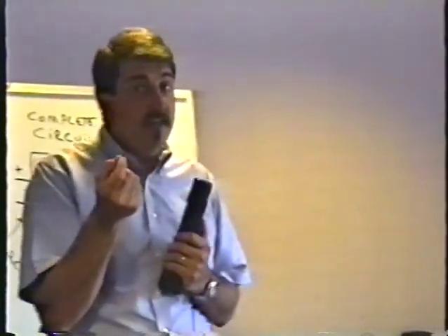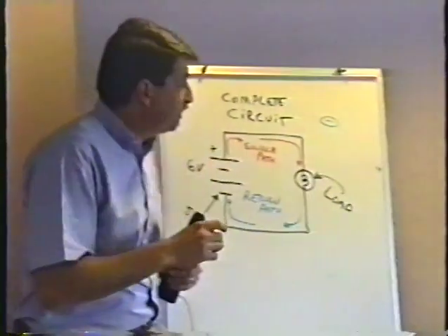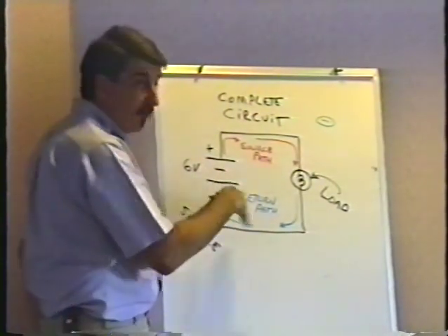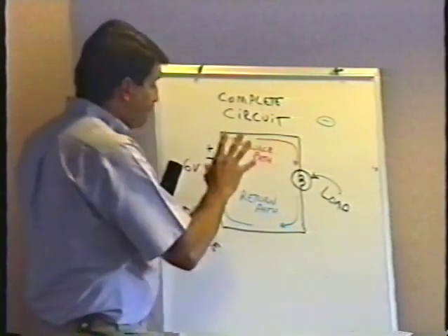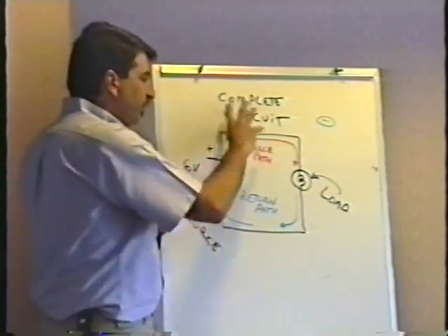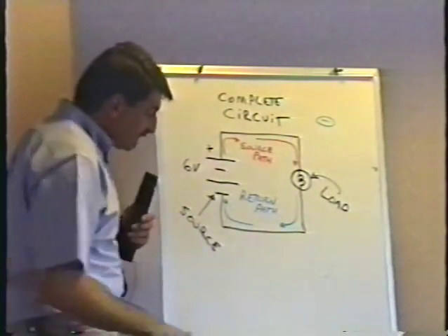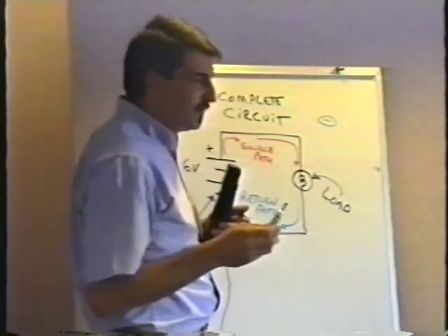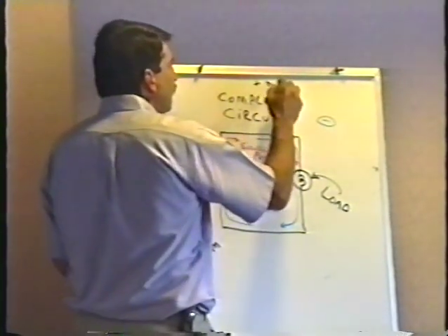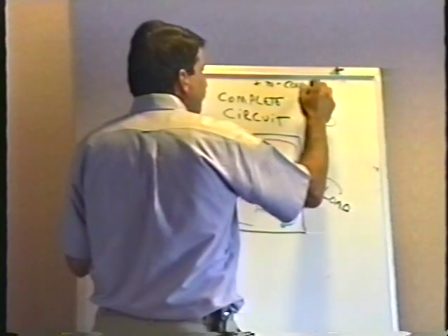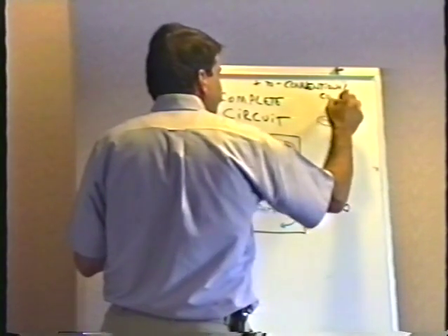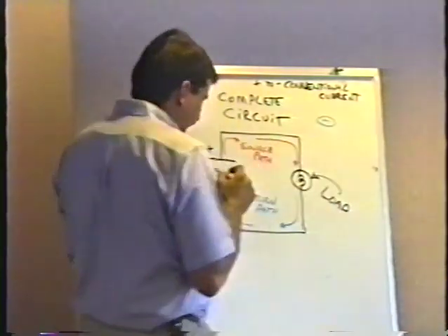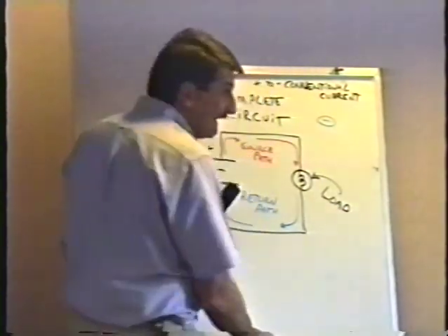Well, when we discovered hundreds of years later that electricity is really these negatively charged electrons, they did not change the way they draw schematic diagrams. Schematic diagrams are still drawn kind of backwards. They are drawn as if electricity was some kind of invisible fluid flowing from positive to negative. This concept of electricity flowing from positive to negative is known as conventional current. It isn't really the way the electric current flows, but it's the way we draw the schematic diagrams.